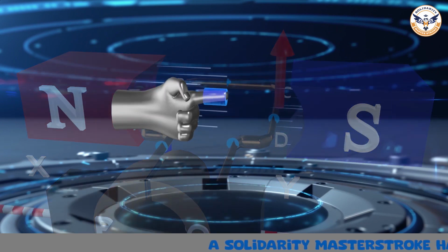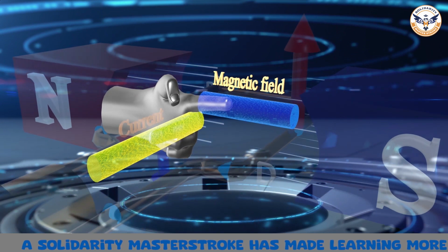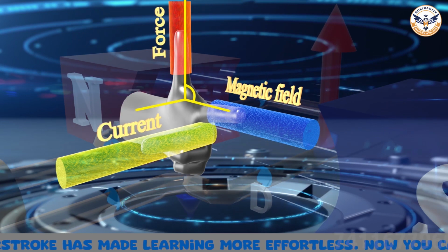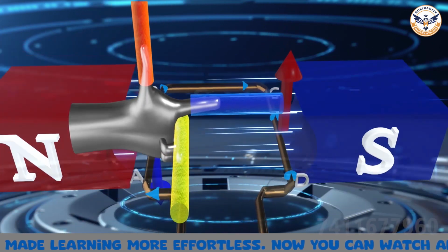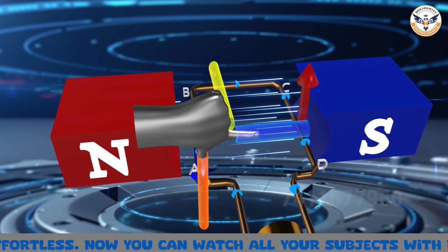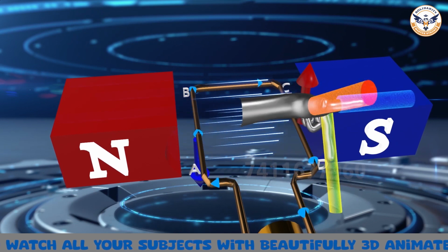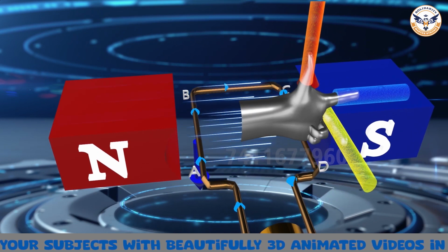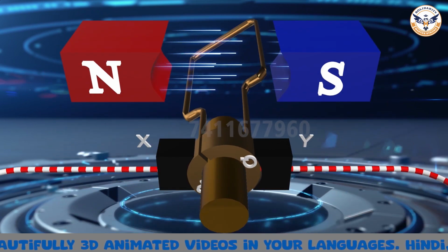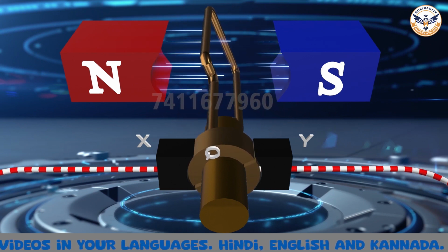On applying Fleming's left-hand rule, we find that the force acting on arm AB pushes it downwards, while the force acting on arm CD pushes it upwards. As a result of these two forces, the coil and the axle O, mounted free to turn about an axis, rotate anti-clockwise.